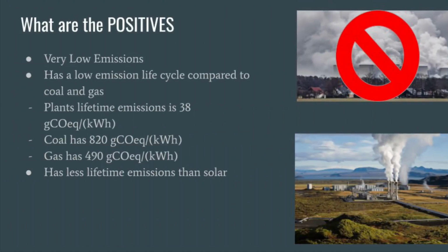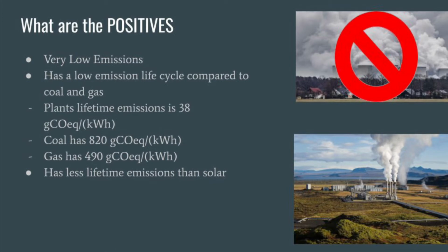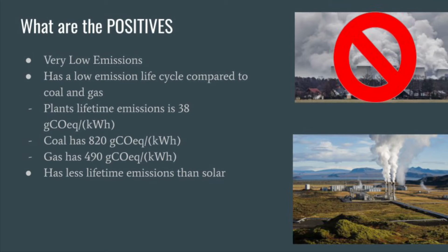Alright, now we will be going over the pros and cons of using geothermal energy to see how it impacts the world. First, with geothermal energy, some of its positive impacts is that it has very low emissions, which can pertain to its byproducts of steam that is used and then recycled back into the system. So not a lot of CO2 is created, and it's very helpful to the environment and much more efficient than a gas or a coal plant, and can even be more efficient than solar and other green energies at times.